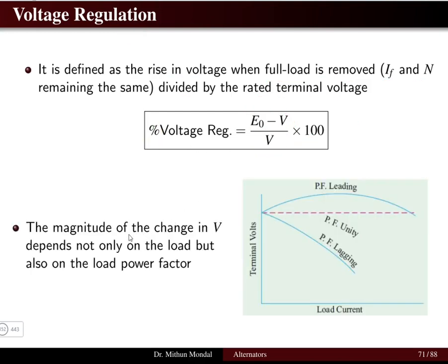The magnitude of the change in the voltage depends not only on the load but also on the load power factor. We have discussed this in the previous lecture, the effect of armature reaction. So the voltage changes when there is a change in the load, and the power factor also plays a very important role in the voltage drop.